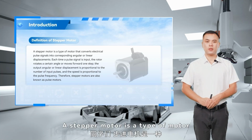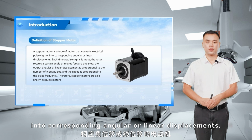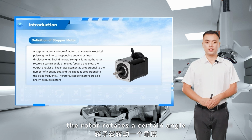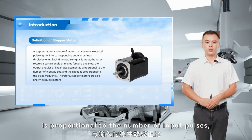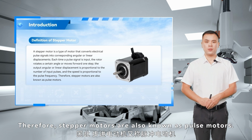A stepper motor is a type of motor that converts electrical pulse signals into corresponding angular or linear displacements. Each time a pulse signal is input, the rotor rotates a certain angle or moves forward one step. The output angular or linear displacement is proportional to the number of input pulses, and the speed is proportional to the pulse frequency. Therefore, stepper motors are also known as pulse motors.